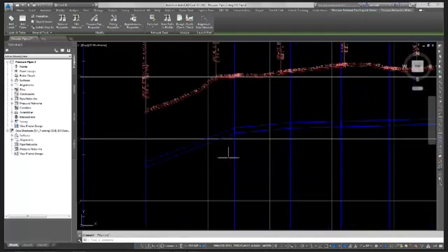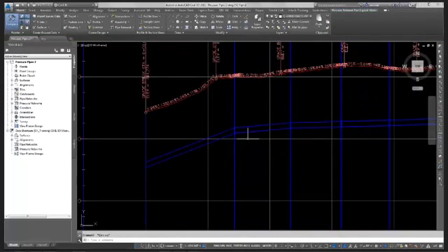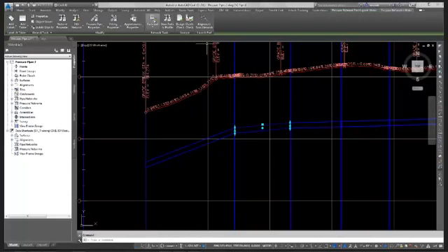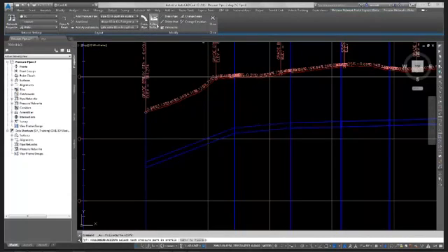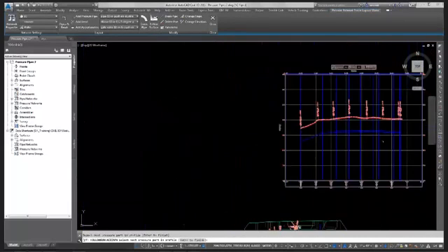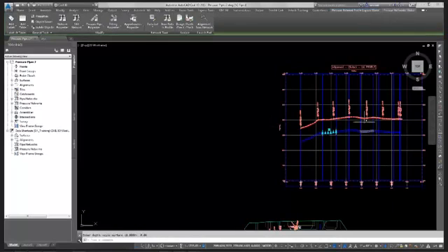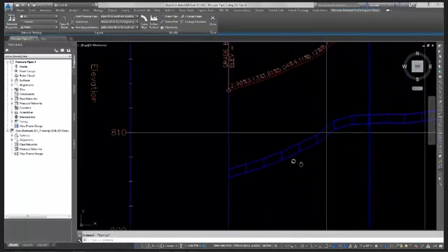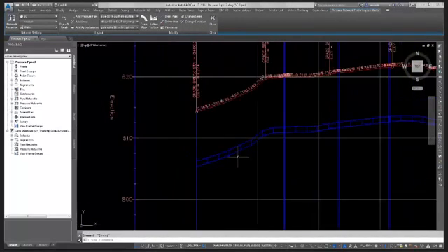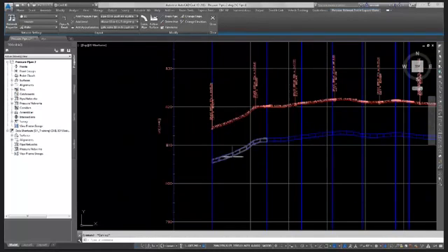It looks like that. It's not too bad, but when I go into profile view and I say follow surface, and I pick that one to that one, surface below, we're going to go 8 feet. It breaks my pipe up into little tiny segments, which makes it a little less pleasing.